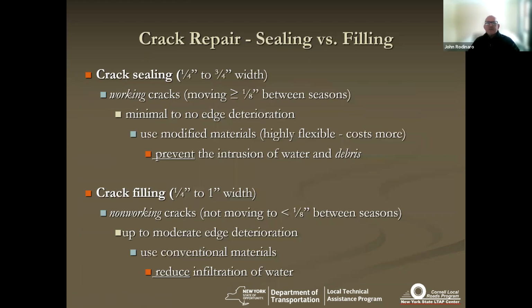All right, in terms of your specific crack repair activities, you've got your sealing versus your filling. And crack sealing really is targeted at working cracks. That's cracks that are moving based on temperature, in the season, in the weather.